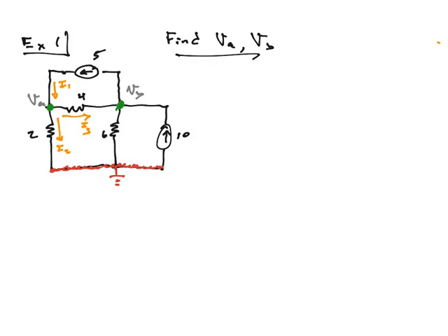What about at B? At B, notice the 5 is coming out of B to go to A, so that's still there. But I already called that I1, so I just relabel it I1. It's the same current. It goes out of B and into A. It doesn't change its name. Likewise, I3 goes from A, hits the 4 ohm resistor and goes to B, that's all I3.